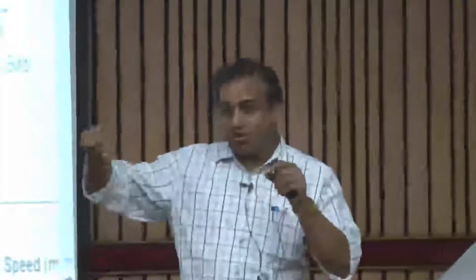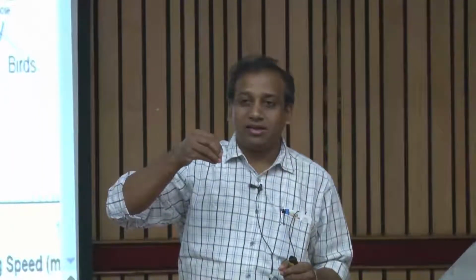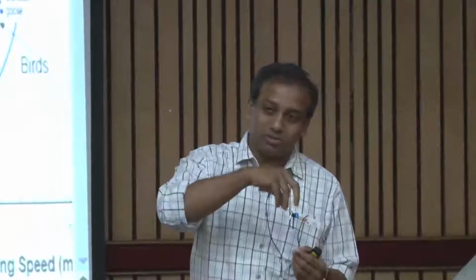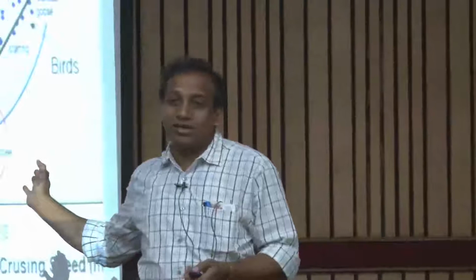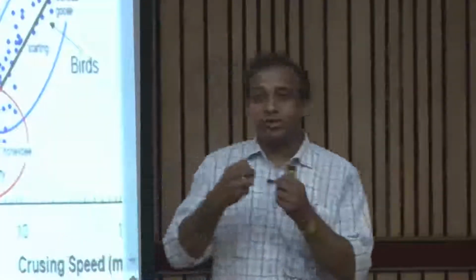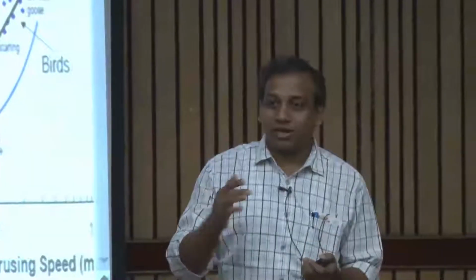Actually, that's what I said, that these vortices forming on the leading edge and the other part of the wing, because these are done with zero advance ratio, meaning there is no forward velocity, some of these vortices will shed also. And during this reverse flow, this vortex and the opposite vortex will form. Their interaction depends on their strength, as with the ejection phenomenon I showed, so it will depend on parameters.